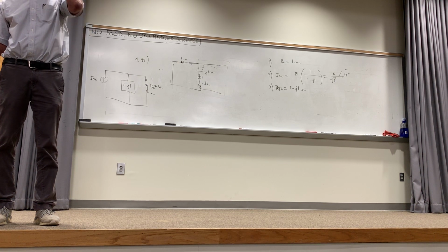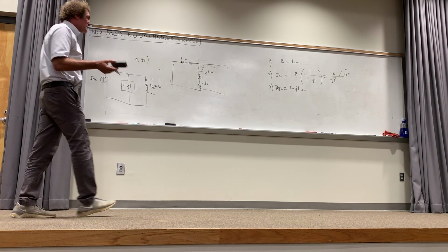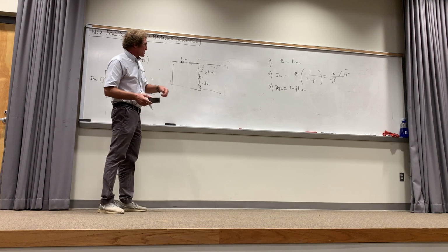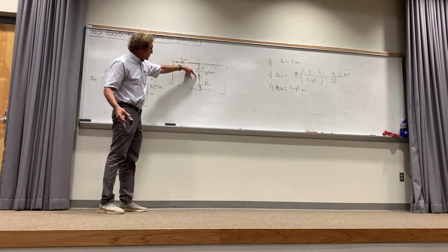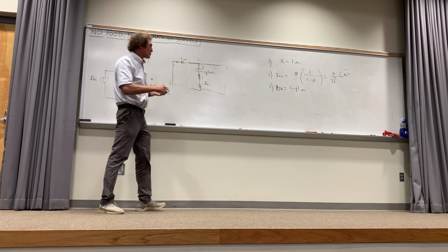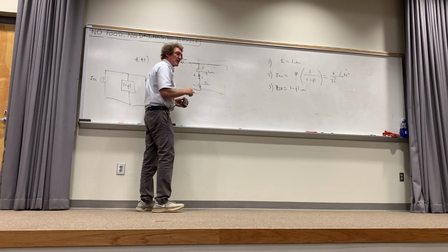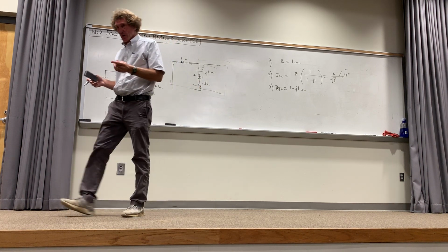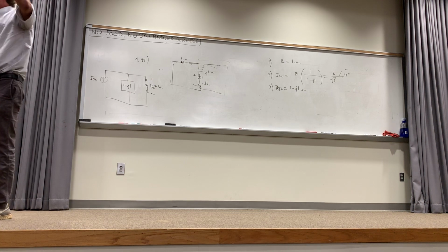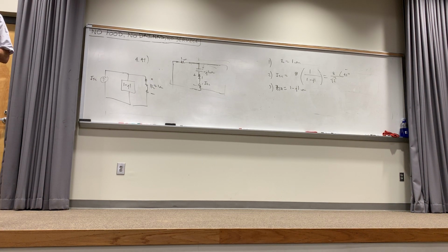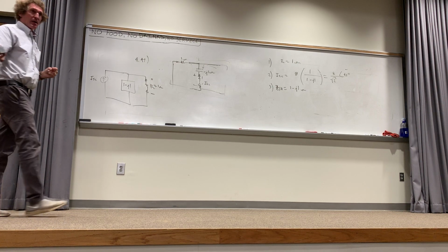I know you think, well, the resistor here, see, the way the short circuit current goes, it's from the positive to the negative terminal. The original problem had this as the polarities for the voltage. So the short circuit current would be going from the plus to the negative terminal through there. Good. That helps.